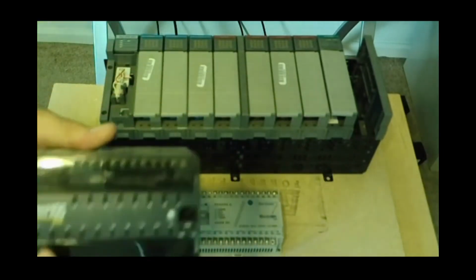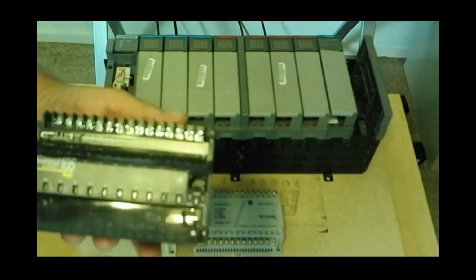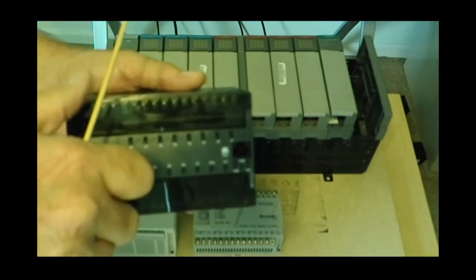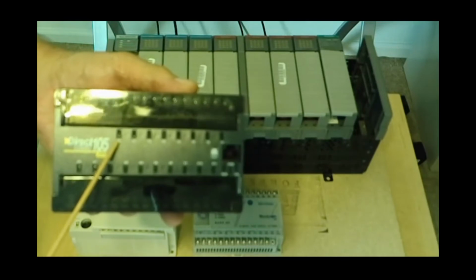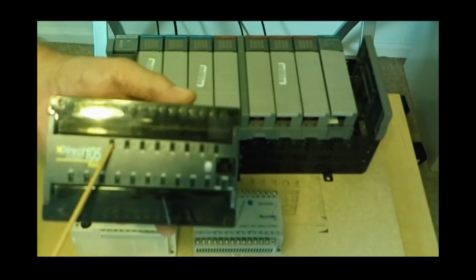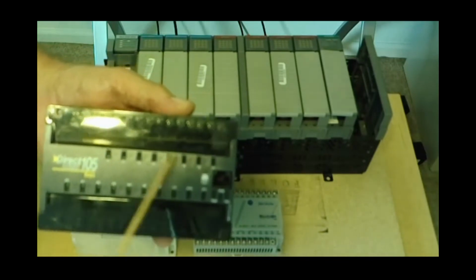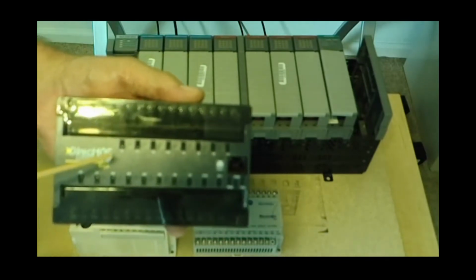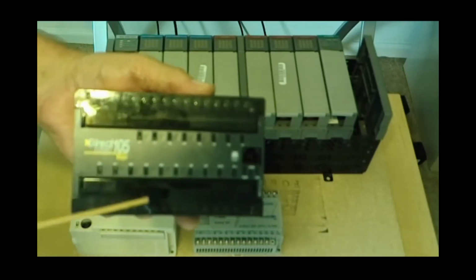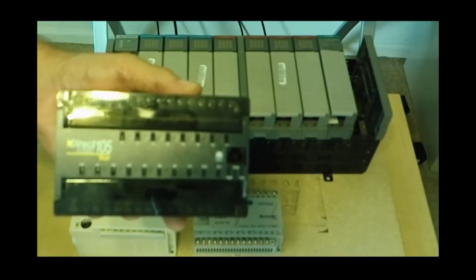Here we have another one right here. It's going to be a DirectLogic 105. This is Automation Direct. These things are very good. They're high-end, they're not complicated or confusing, and they're easy to work with. Right here you've got a different set of numbering, Y0, Y1, all the way up to Y7. Well, on the Allen Bradleys and all the others, X is input, and I is input and O is output. On these ones, anything made outside of the US, it's a different numbering standard. X is input, Y is output.